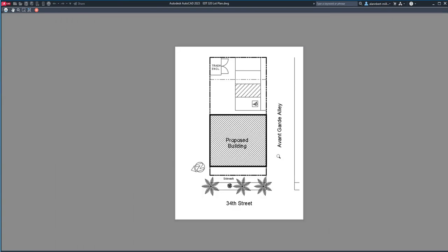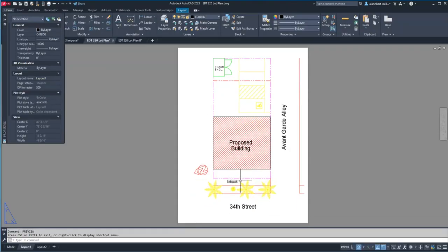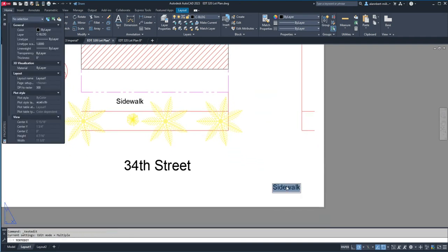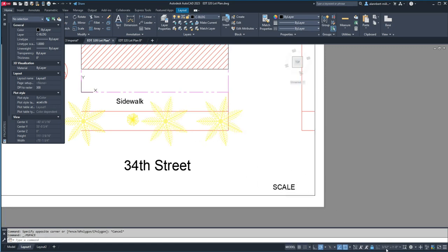And then the last thing that we wanted to do is put here, maybe in a corner, the scale that this drawing is in. Okay, so press escape, and then I'm just going to copy this little bit of text here, and double click and type in scale 1/8. Oh no, what scale is this again? 3/32, I believe. Let's just double check. Double click, 3/32 to foot.